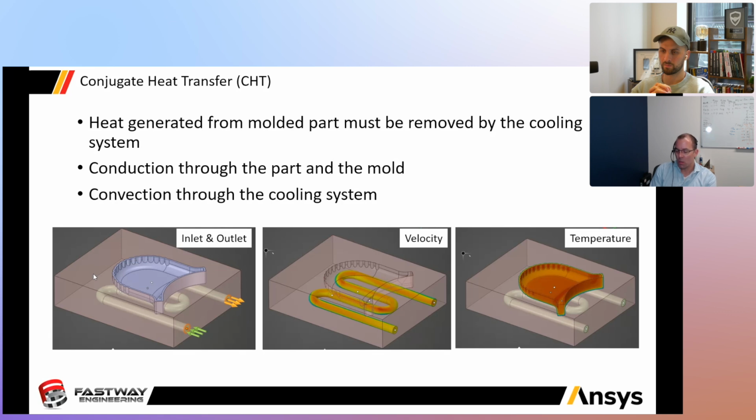So what you can do is easily calculate. This is Excel math. This is linear math. We don't need simulation for this. Say this is the starting temperature, this is the ending temperature, this is the time, and this is the heat capacity of the material that I'm cooling. Real simple stuff, and I can convert that into a thermal load.